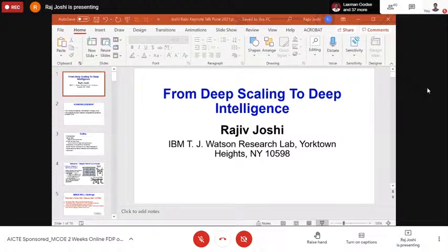So this is an example. What is shown here is the IBM P8 processor. And so you can see the sizes here, roughly. These large caches are 512 KB, then L3 is 96 MB, and it is predominantly embedded DRAM. And then you have this 6 transistor cell. This is the circuit diagram of it. And the 6 transistor cell stores the data, 1 or 0.